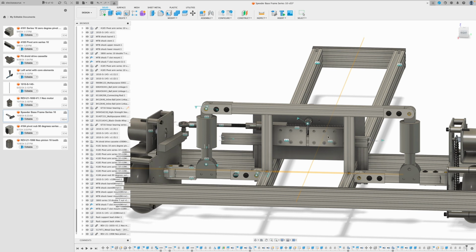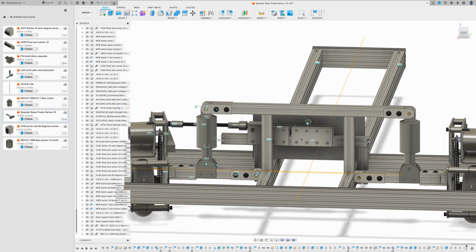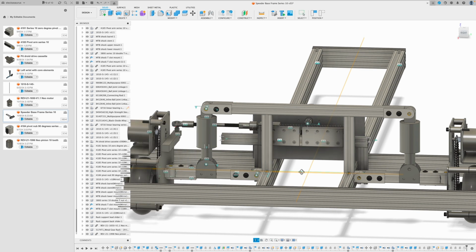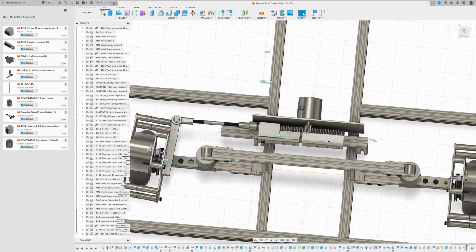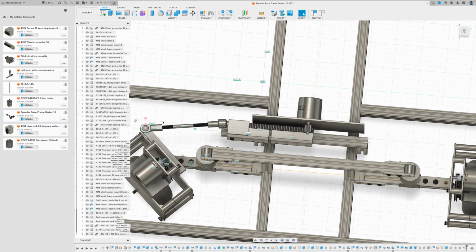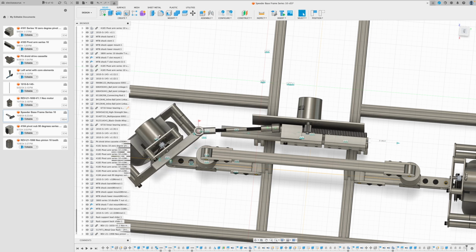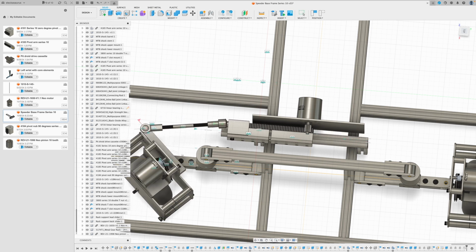So this rack, when it moves, it pulls. In this case, it pulls the wheel over, and if you move it the other way, it pushes the wheel over. And if I move to the top, we can see the angles of this tie rod changes over the course of the movement, right? So this is not a completely linear equation between rack travel and the degree that the drive wheel turns. It's something different.